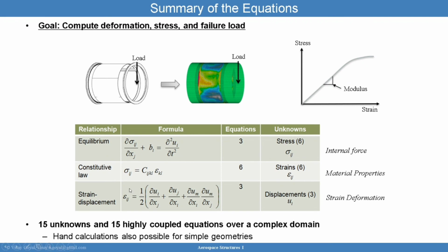We can put all the equations into one single equation. For example, I could use a stress relationship here, and I can plug in strain for deflection. So I can take this whole expression here, which is in the book for this course. We didn't discuss these nonlinear terms, but for small strain approximation, this is what we're going to be using.